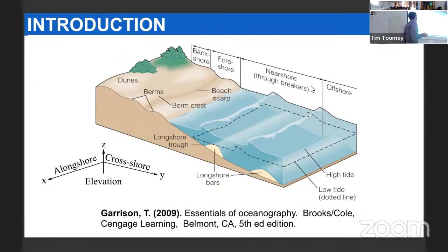So the idea of equilibrium beach profile theory is the following. If we take this forcing and freeze it, so we keep it at the same value, then there will be this change, this movement of sediment, until a certain point where the beach reaches a state where there's still sediment moving, but the shape of the beach does not change. This is when the system has arrived at equilibrium. Now if we change the forcing, again there will be a change of the shape of the beach bed, and again it will reach a different equilibrium state. So it depends only on the set of parameters that describe this forcing.